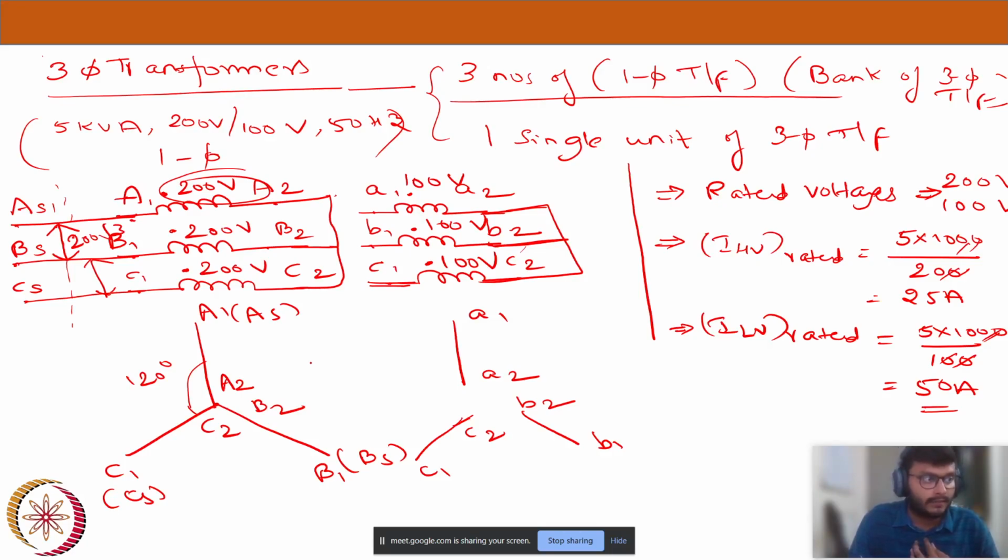We will discuss three-phase problems, Vinod. Let me first discuss the star-star connection and one star-delta connection, and we will do numerical problems on star-delta and delta-star. Okay. So the moment I shorted A2, B2, C2, my secondary also became a star connection.